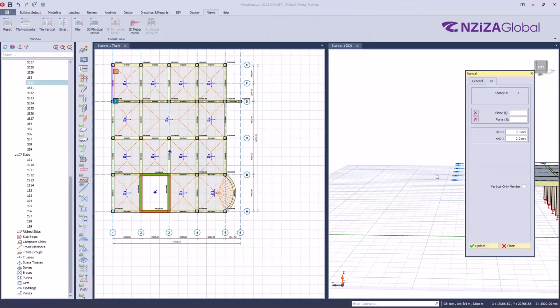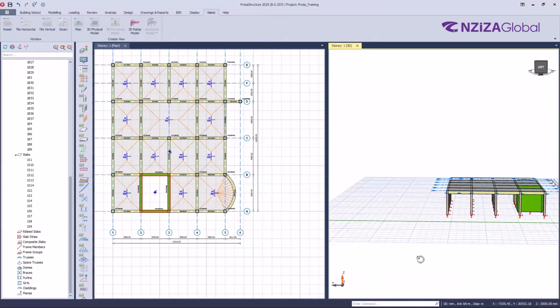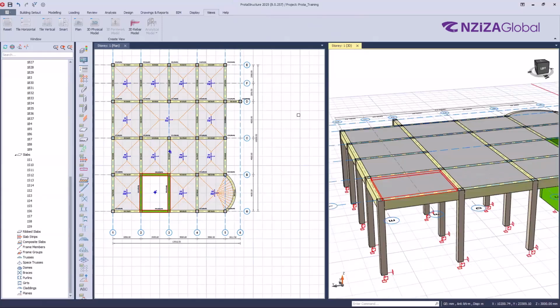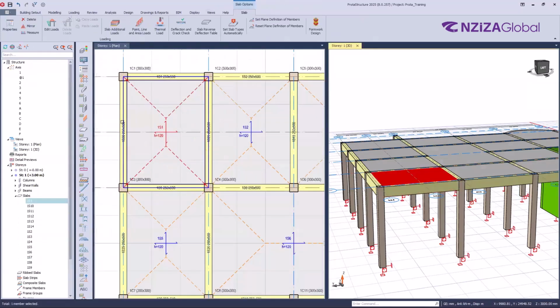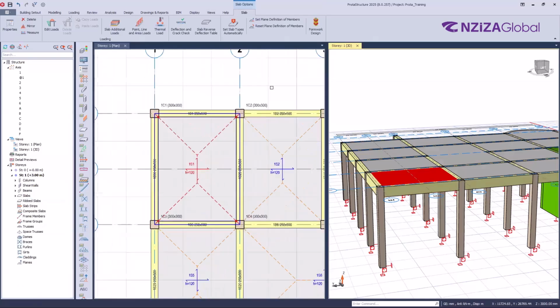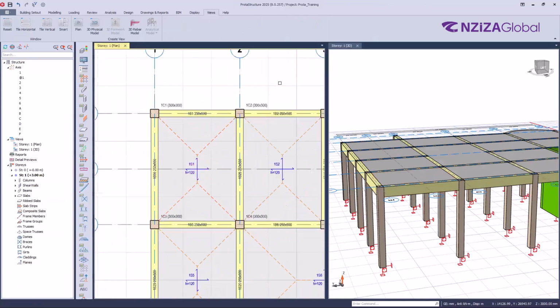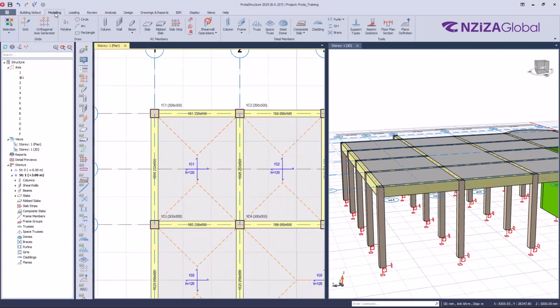So that the slab may be lowered down, I'm going to use the plane definitions. Let's see how to use the plane definition. This slab is this one in the plan view. So let's create a plane definition. To create a plane definition, it is under the modeling tab, all the way the last option under tools. You will see plane definition.